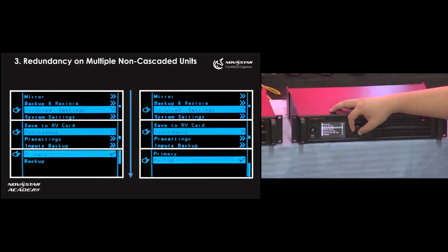Press the knob and do a quick configure: 3 rows, 4 columns, and 12 cabinets, and we give the correct data flow. Okay, we make everything work properly, and we move to advanced settings, and set the redundancy as backup, and save to hardware.